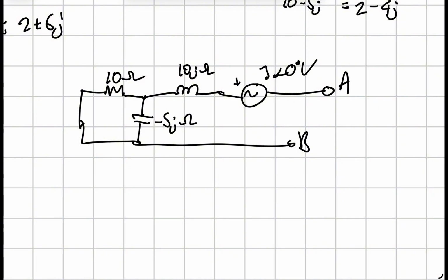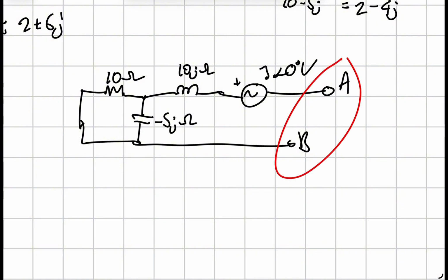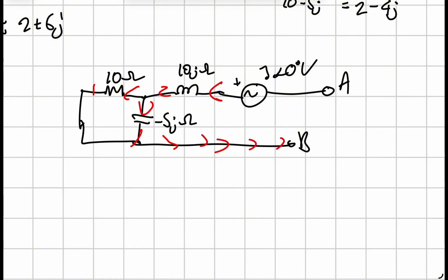But you also realise that you've got a parallel circuit. That means your voltage is going to stay the same, because it doesn't matter that your A and B are far away from that. It's still parallel, so it'll be the exact same, but it goes to B before it goes to A, the positive, as you can see from here. So it will be minus 3 volts for that second contribution.